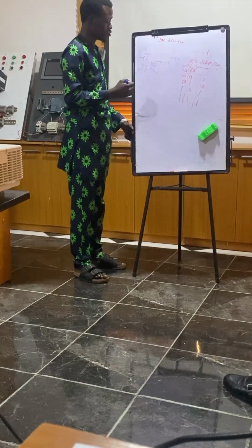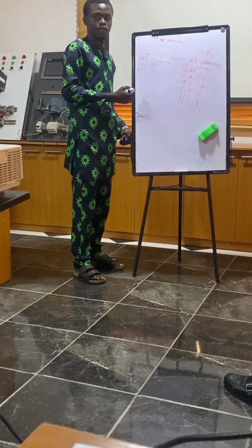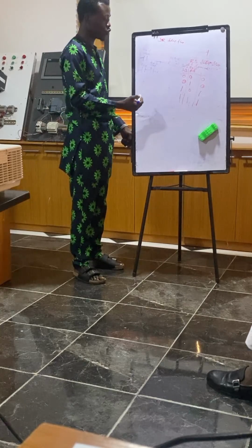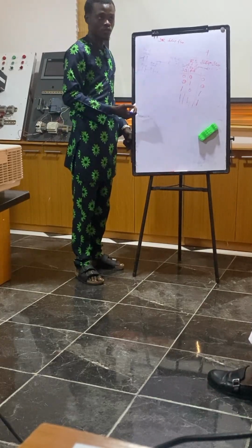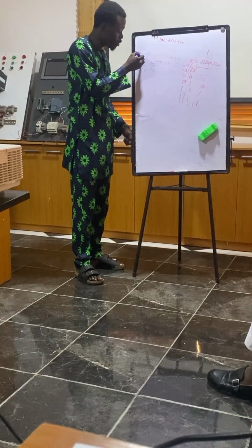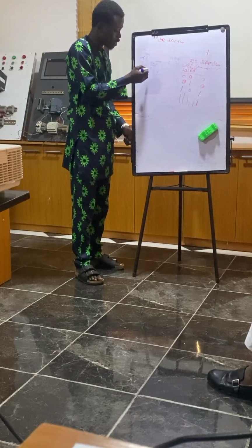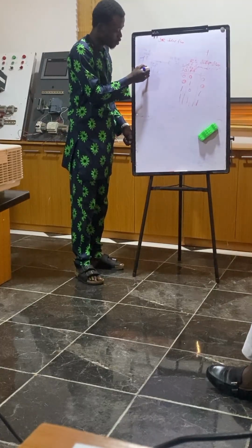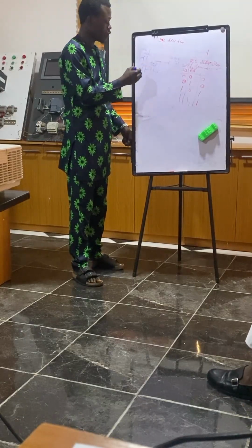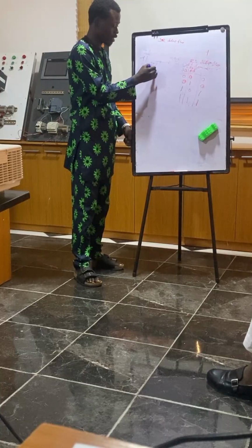I0.0. Okay? So let's take this through our test as well, to see if it's going to pass. The first one is when the two of them are not pressed. When the start button is not pressed, there will be a 0 here, and there will be a 0 here. Because of that, this one gets inverted.